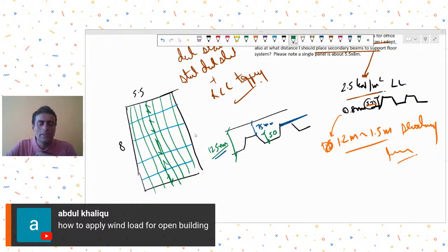That means if you, let's say, have an I-shaped column, then you calculate the CF for your I-shaped column, and then as per the column exposed surface, you calculate the wind loads. Same thing you do for the beams also, and in that way you apply the wind loads for it. So if I were to show you a sample, it's given in a table. So you have these tables, table 25. Wait a minute.